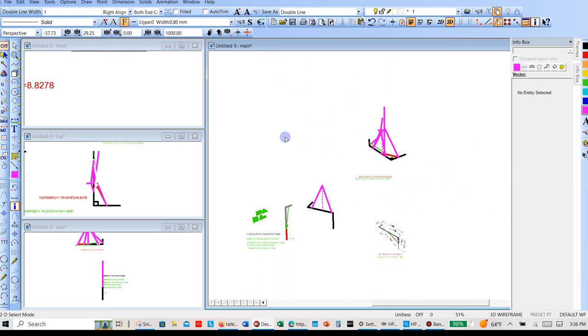All of it in rigging up like a steam pipe that has 3 axes going different directions, and having to pick it in position with just three slings, mostly with the 2. You could do it with 2, but it's much easier to do with 3. So if you didn't have the headroom or you couldn't use it out there, you could still pick it with 2 and something like this.